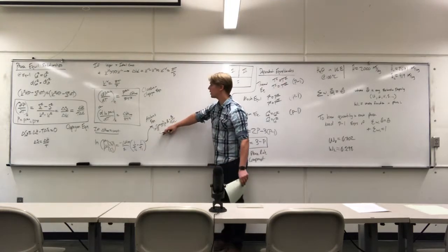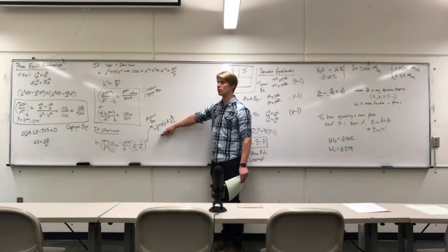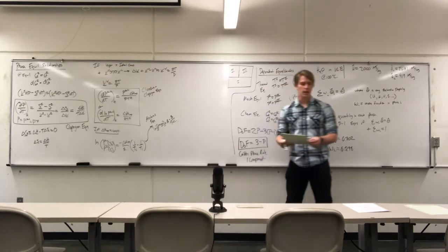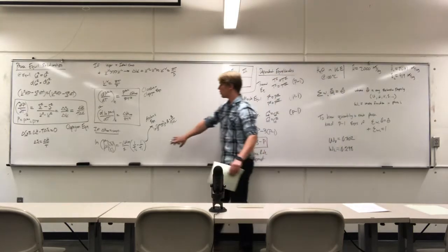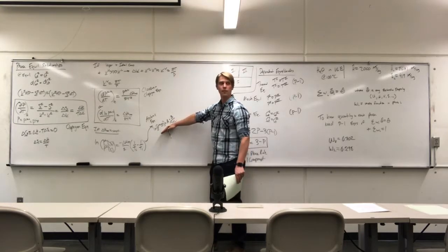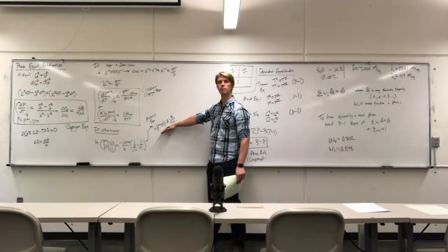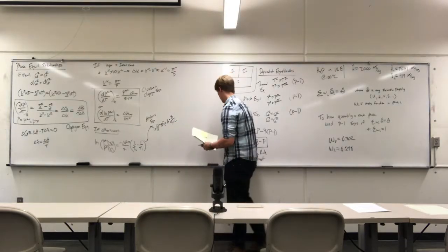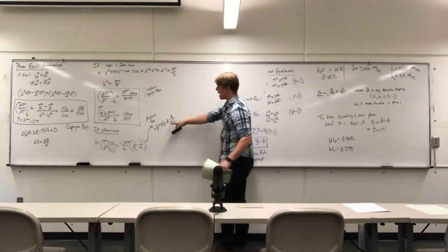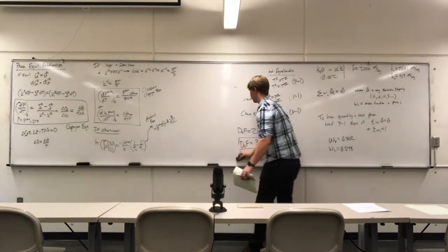So the Antoine equation's functional form is chosen because it matches theoretically the true functional form that we would expect in a real vapor-liquid equilibrium system. So they selected this to correlate and fit the data because it has the functional shape that seems to work the best. So that's where the Antoine expression comes from. The coefficient A is in many regards related to the heat of vaporization of the fluid itself.